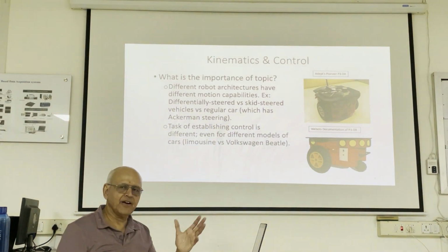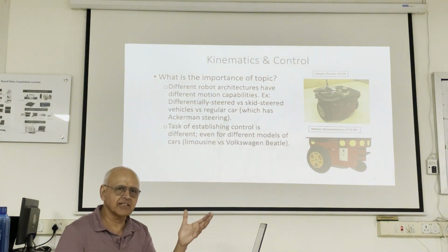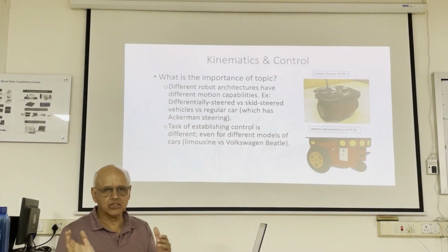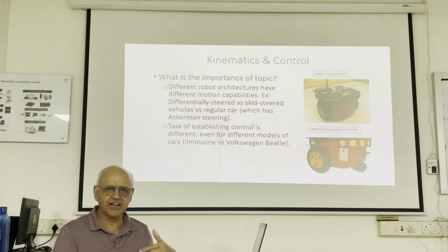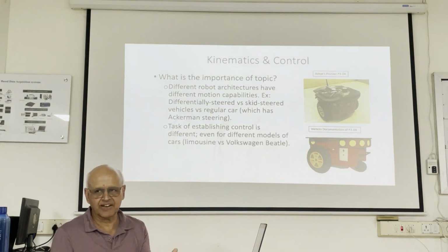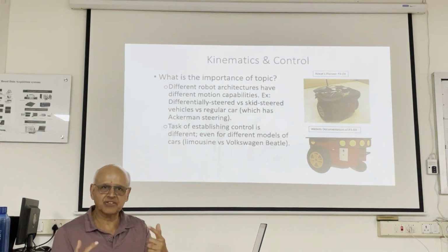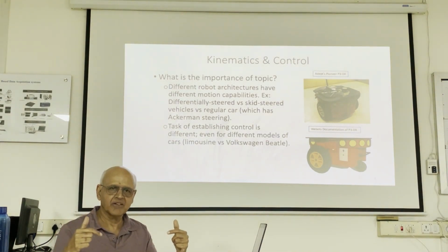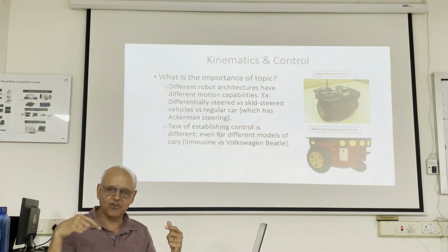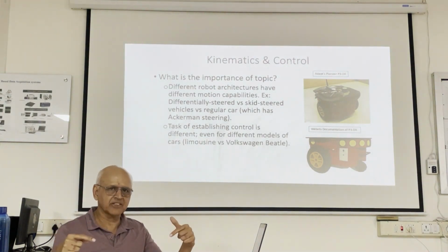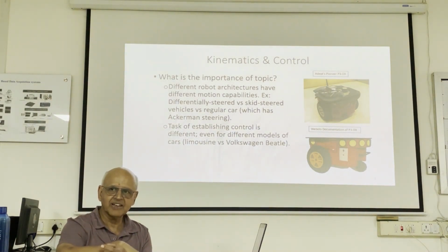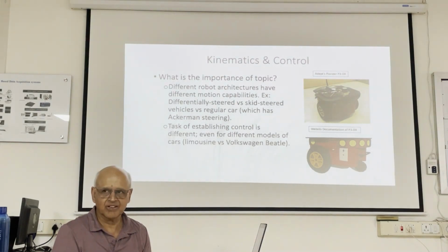So if you want to turn left, you spin the right wheel faster than the left wheel. If you want to turn right, then you spin the left wheel faster than the right wheel. And then you can do the same thing with backwards motion also. You can turn them backwards. Now, if you turn the right wheel forward and the left wheel backwards at the same speed, you will spin in place. Is that clear? So, all kinds of sophisticated contours are possible with this robot.